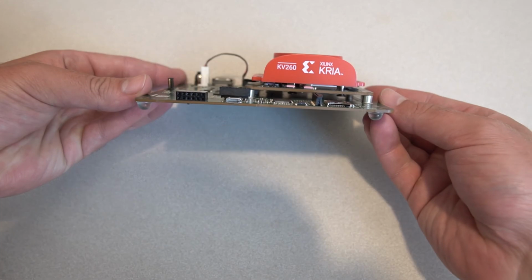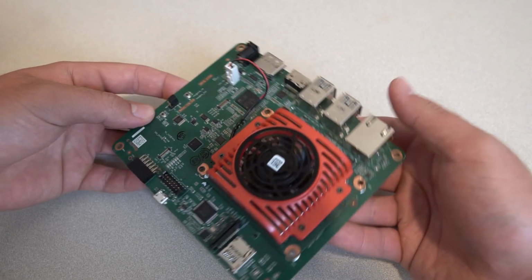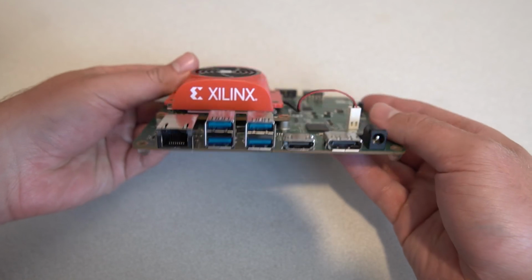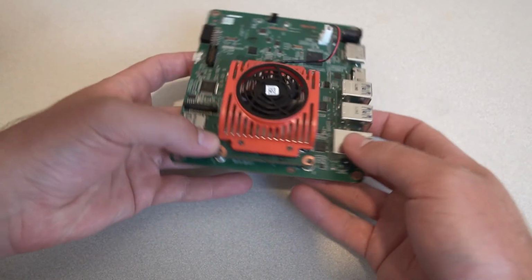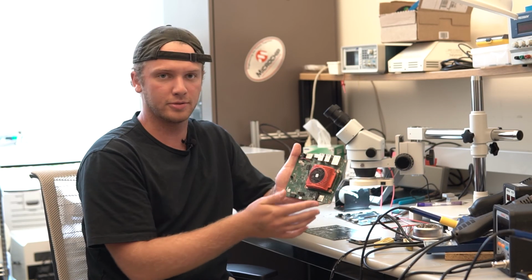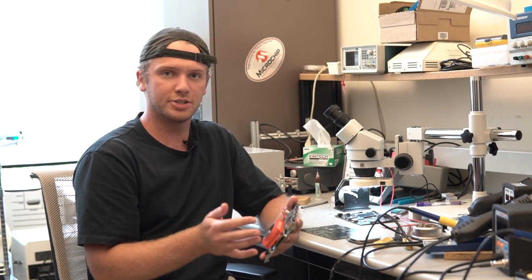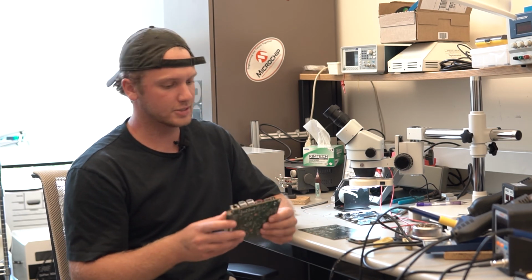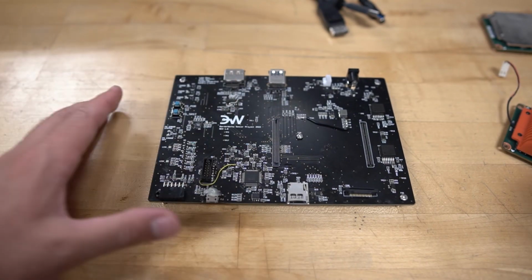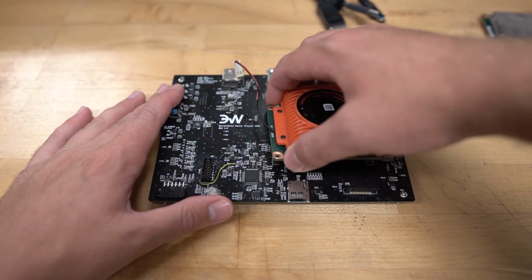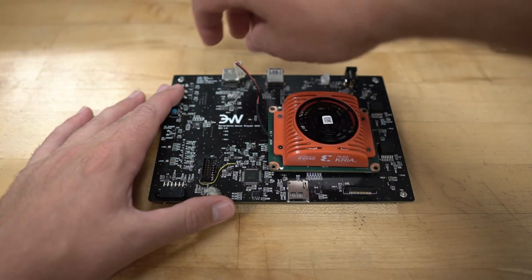So for this chip, we have a carrier card that we designed. This here is a dev kit, so we bought this, and basically it comes with your Kria SOM, and then this plugs into this board on the outside here, so you have all your peripherals like USB, HDMI, DisplayPort, power, your SD card, and a few other things. Essentially what we had to do is take this board, take only the parts that we were going to use, and then create our own custom board for that.